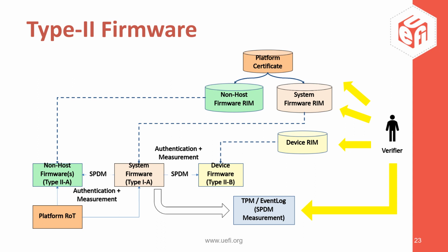The SPDM protocol is the standard from the DMTF organization. The benefit of using SPDM protocol is that the measurement format is standardized. We can have a generic verifier to parse the SPDM-based measurement information. If we standardize that in the TCG PFP spec as well, we can get that from the TCG event log.